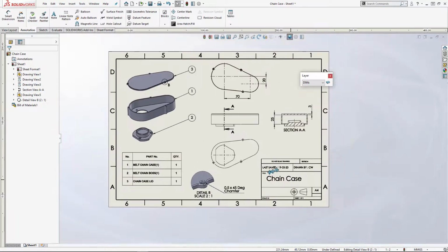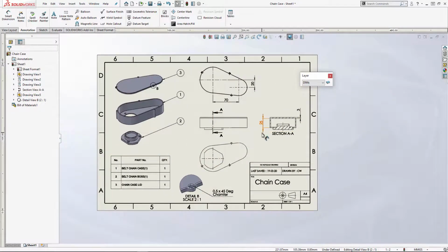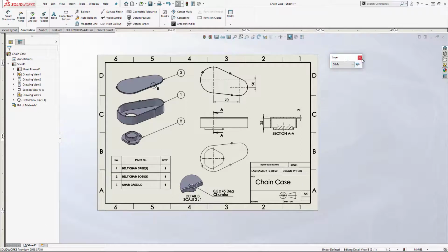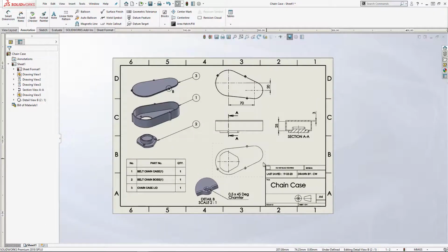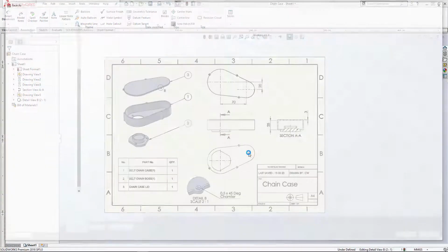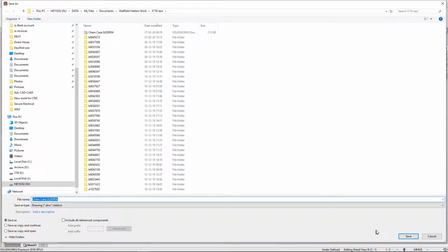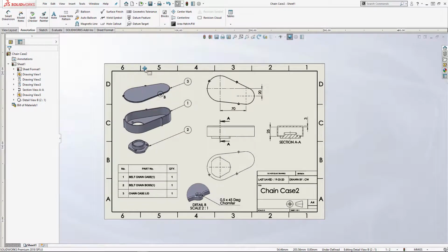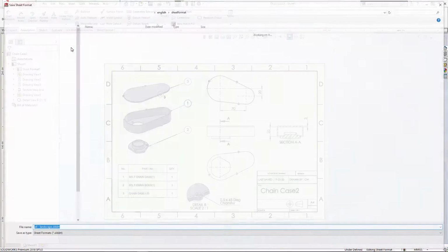That's kind of a brief introduction to quite a few different drawing skills. As I say, some of them are specific to assembly drawings, some of them are just generic SolidWorks drawing skills. I think the last one that we'll cover is, obviously you would want to then take a save of this. So we could save that wherever we're going to save it. In this case I already have a copy in there, so I'll probably put a number 2 at the end of it. So yeah, you can see it's auto-updating the actual name of it. So say that sheet format was the format that we wanted to then take forward into all our future drawings. You could go to the File menu and say Save Sheet Format.